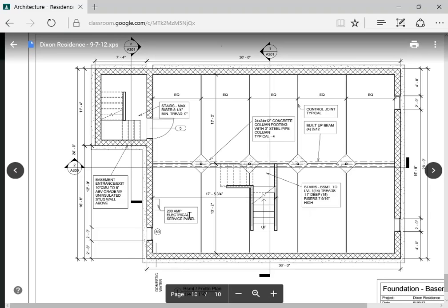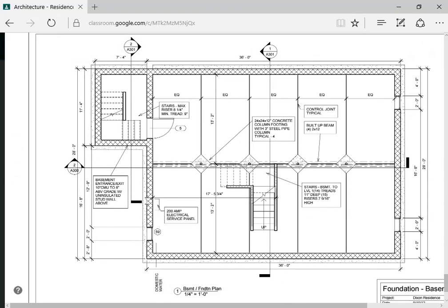You can also show mechanical equipment, mechanical and electrical equipment. If there are any windows, you need to add the windows. And the biggest thing with windows is very often in foundations you put in hopper windows, which are very short windows, often 16 inches, sometimes as small as 8 inches, sometimes 24, and they're basically sized for a modular opening. And you have to remember that the foundation is typically covered with dirt, so it's mostly underground, so we very often have very short windows in the basement.